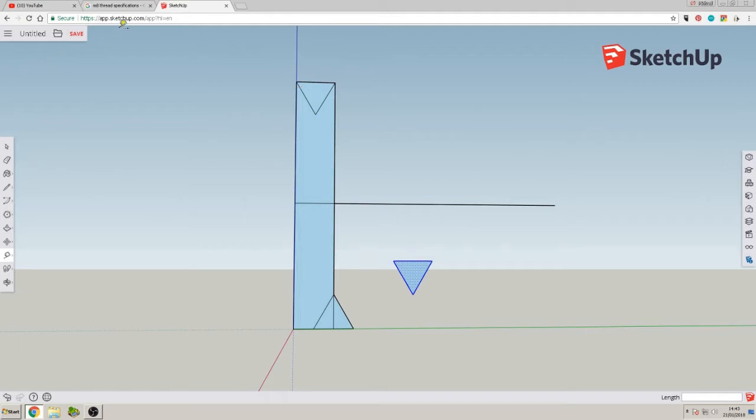That sounds about right. And that would mean, let's just quickly put a construction line in there at the core, should be about 6-ish, 5.834, yeah. And if you took into account that at the bottom there's going to be a little thing, then yeah, it is about 6-ish. That's why the tapping drill for that would be 6.